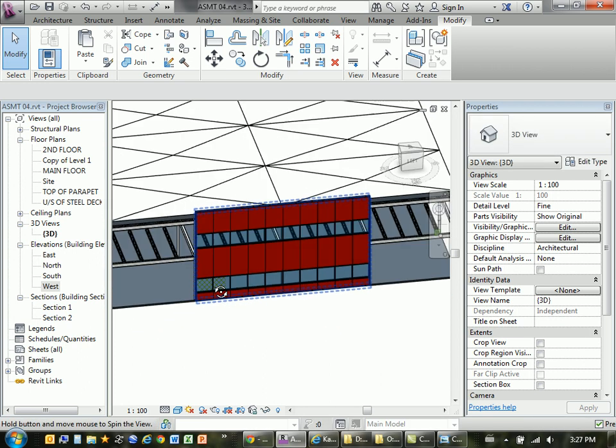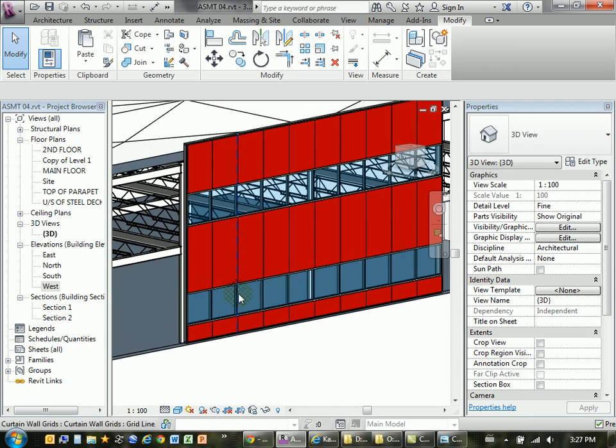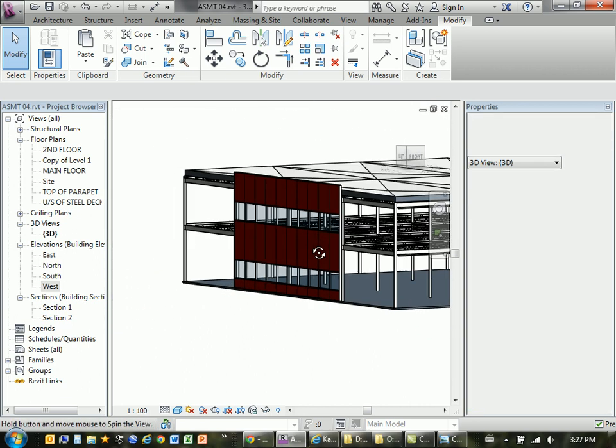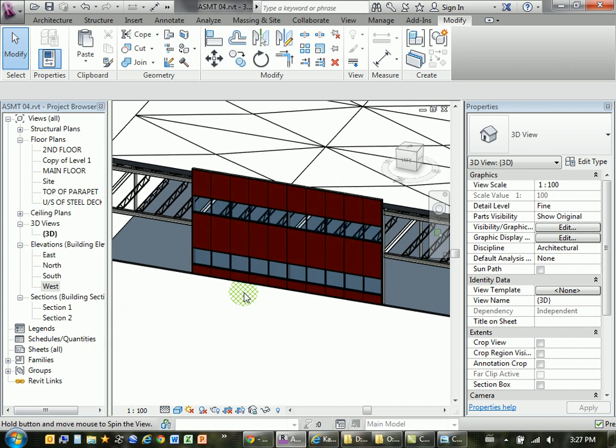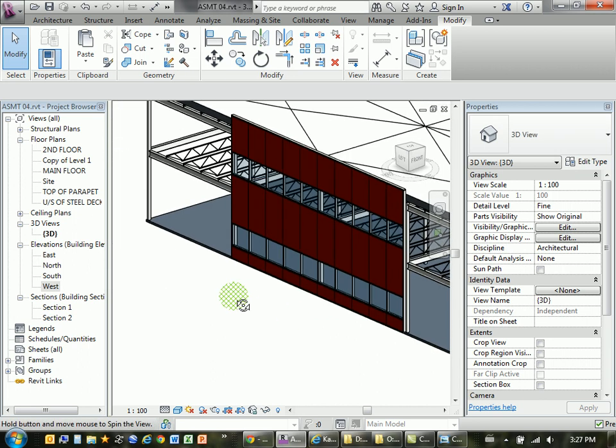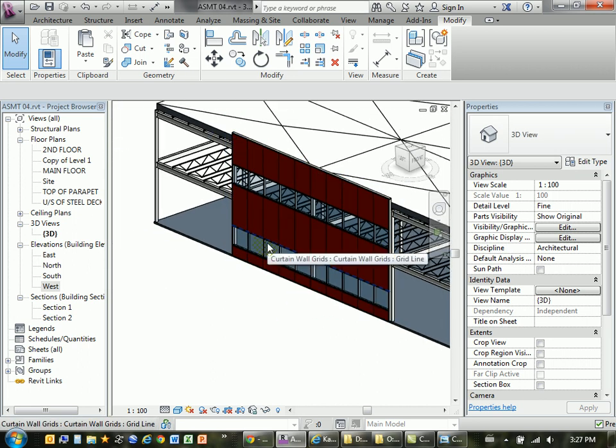And that leaves me with my curtain wall view glass panels and spandrel glass panels. The idea here, of course, is just to put those in the area so that if you imagine somebody standing inside there, they've got a view roughly above their head to a little bit below their knees or around their waist. So the ergonomics come into play there. Last thing I'm going to do here is just set the grids in the right place with regards to the planning grid.